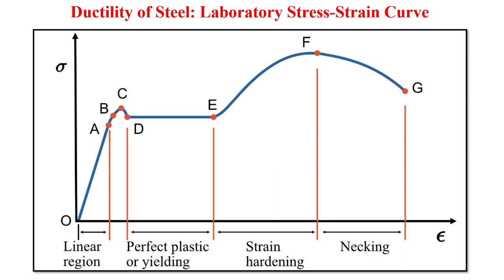It can be seen that stress strain relation is linear in the elastic range, whereas upper yield point C is reached and then stress suddenly comes down to lower yield stress at point D. However, the strain then increases up to point E at constant stress. This represents the plastic range. Beyond E, the strain goes on increasing with further increase of stress, and material is said to be in a state of strain hardening or in a range of strain hardening.